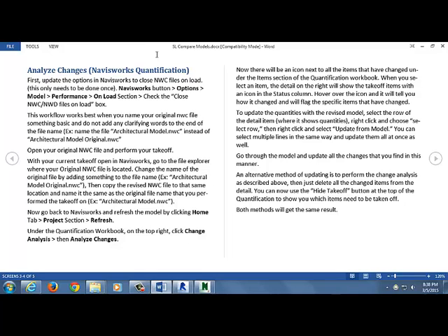So did you already do your takeoff? The first step after you open it is to do your takeoff. Okay, so I did this. So you have it working, and this is 1.1, but you renamed it. Good. So then I opened it. Open it. Now you run your takeoff. So you can either pick a few items. We know that the floor has changed in this, and also the walls. So those are some good ones if you want to just really show what changed. Or you can take off the entire thing.